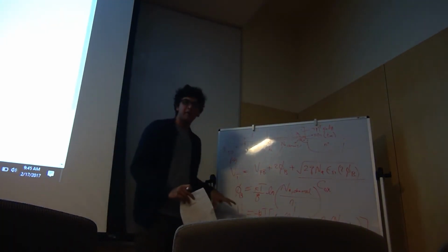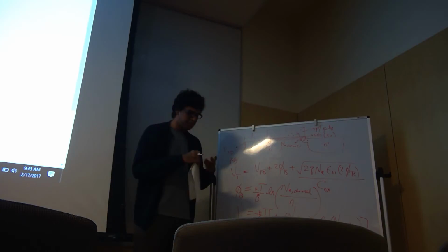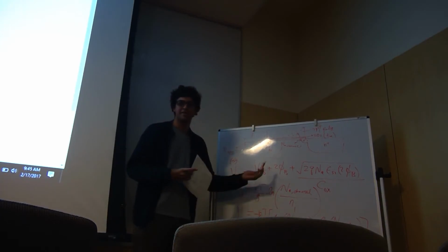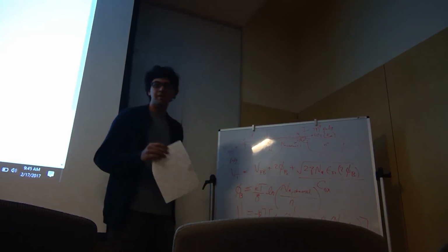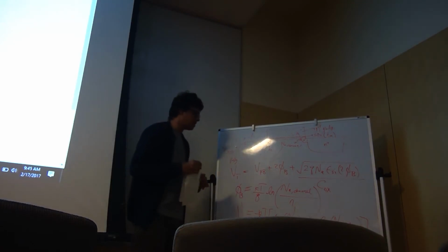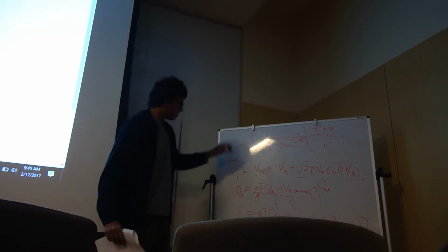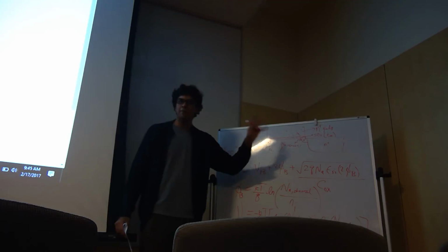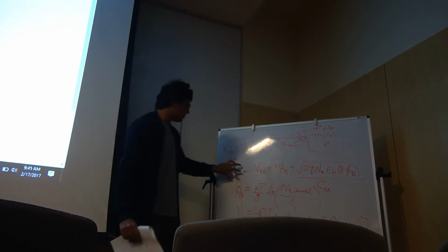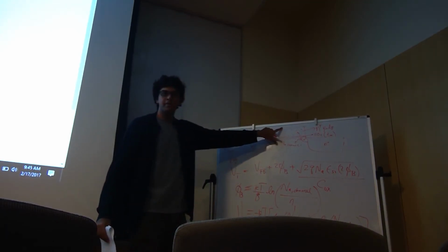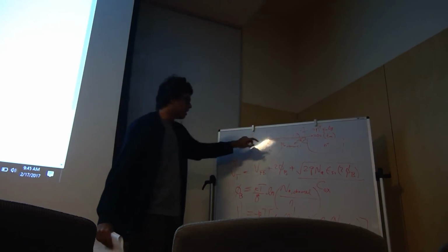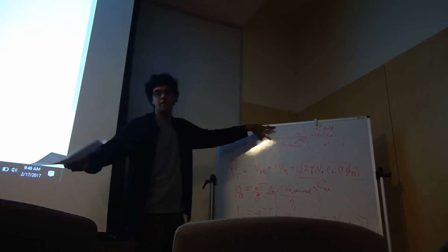Okay, this might look complicated, but it's actually very simple if you draw the band diagram and actually derive it. But for the moment, I'll just tell you what this formula actually means, okay? So it's actually a form of Kirchhoff's voltage law. So Vt is like the voltage you apply between the gate and your source. This voltage is a sum of different voltage drops.